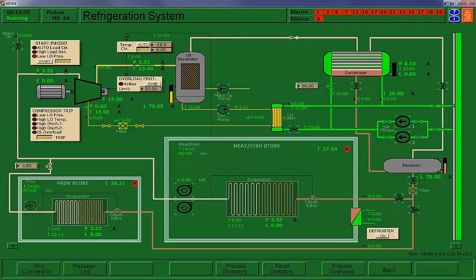All right, first thing I'm going to do is, this is the vent. This vents the main condenser down to the receiver, and then this is the drop. This is the liquid from the condenser going down to the receiver. Both of those have to be open. We're going to open up the salt water cooling water line to the lube oil cooler, and also that goes to the condenser, and start a saltwater pump. We need to put on each of our diffusers. And then when we come back, make sure and put this lube oil circ pump on. That has to be on.